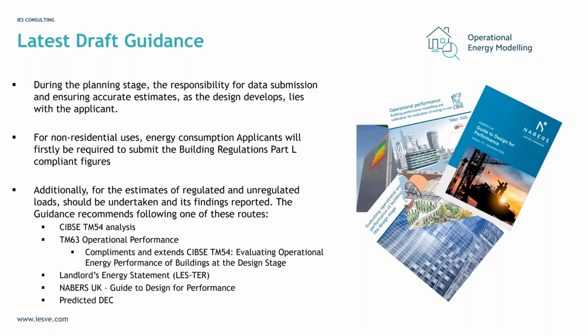Daylight dimming, for example: rather than just applying a reduction factor, by linking the lighting to a radiance sensor, we can model the behavior of the daily lighting energy consumption more realistically through the seasons. We found the impact of daylight dimming versus daylight switching, for example, on one project to be quite remarkable and changed the direction of the electrical design in this respect.